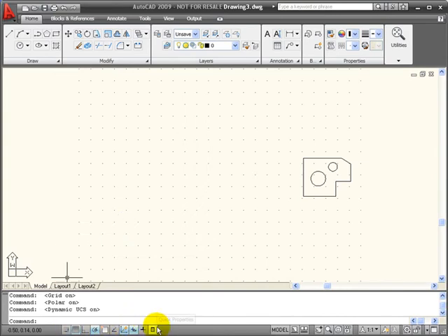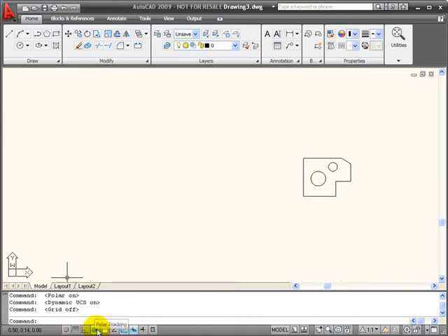One last suggestion before we start. Down here on the status bar we have our drawing aids, and I would toggle these off so they are not lit up. We're going to be drawing mainly with our coordinate entry system, and I've also turned off dynamic input, so we'll be reading our commands off of the command line. To start this object, I'm going to start at absolute coordinate value of 0, 0, which would be my origin. I'll start a line command, key in 0, 0 on the keyboard, and hit Enter.